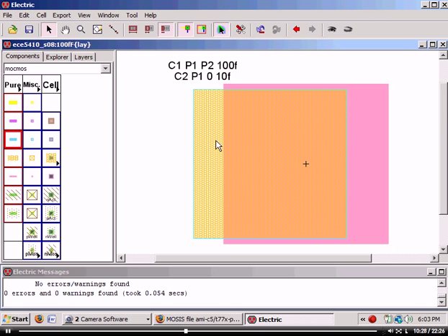Okay. In some processes, you can't put a poly contact over the thin oxide between a poly-poly capacitor. So I can't drop a contact down in here. They make you do it over the field region, so I can only connect over here and over here. In other processes, you can connect over here, and you can connect over the thin oxide. So what I'm curious is, what are the setups here? I think that you can have the polys overlap. You can. So now I'm going to make a connection to them.